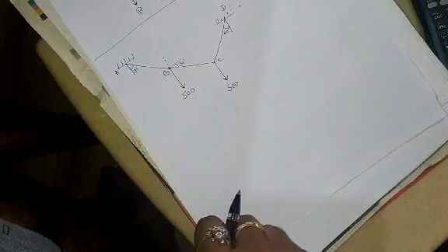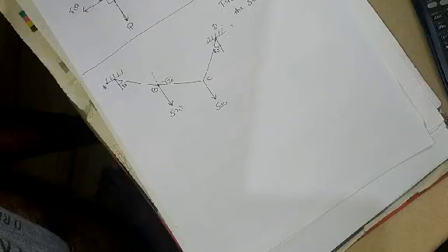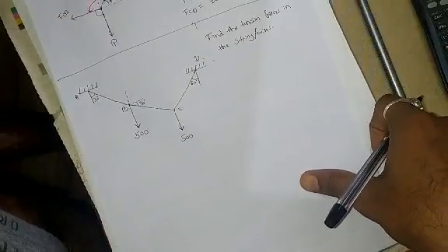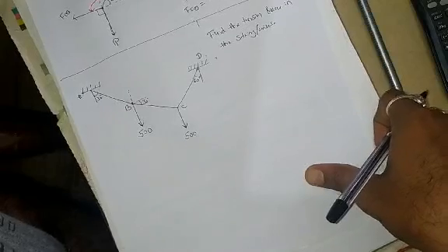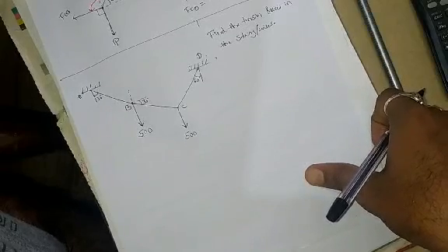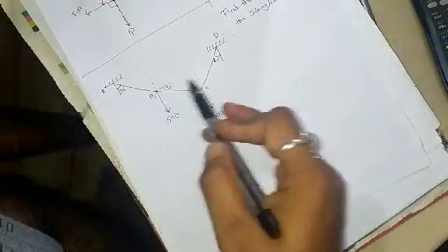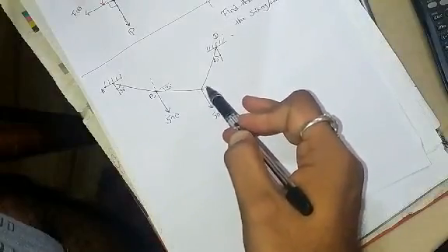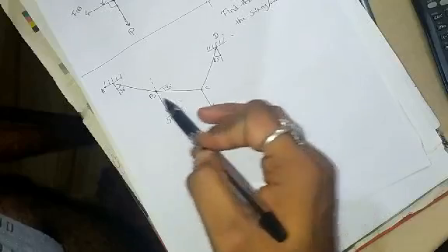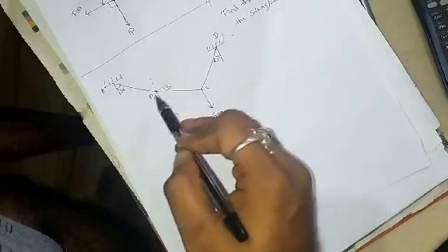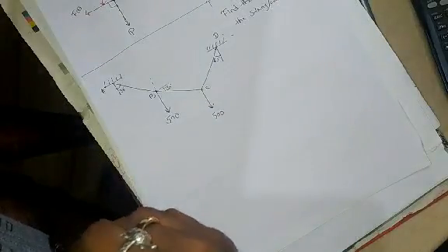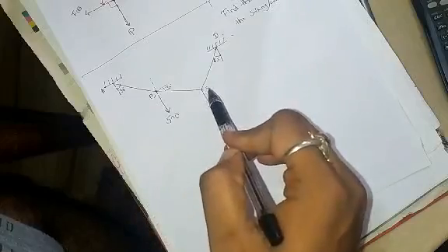So we'll see the next problem. The question is to find the tension in all the strings or wires in the given system. That means we need to find the tension force in AB, BC and CD. We can see there are 2 joints, joint B and joint C. From C the members are CD, CB and this 500 newtons, and from B there are again 3 forces: BC, BA and 500 newtons. First you can consider either joint B or joint C, and then go for the next.